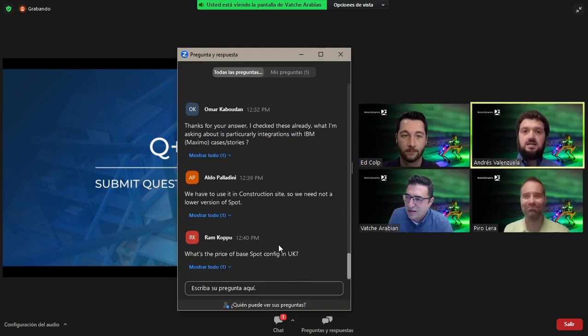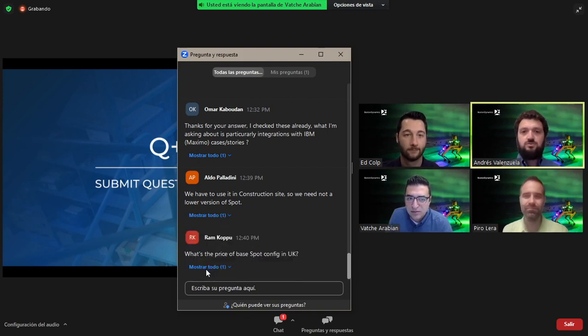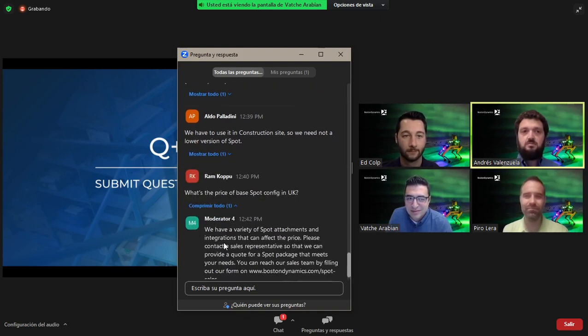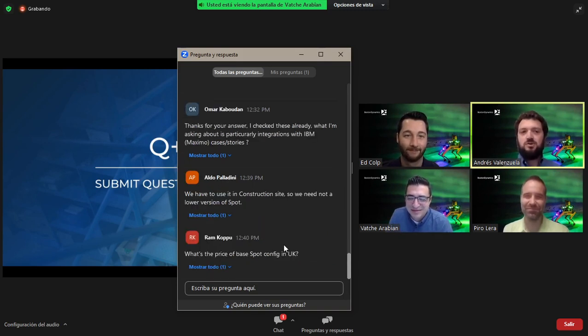I would not expect that to work well. The AutoWalk map recording is going to look at the fine-grained details of the environment for localization. So if you tried to run it in a different environment, unless you built them exactly the same way both times, it's very likely that the robot would have trouble localizing in the new environment. It's really meant to record in place and then execute in place.